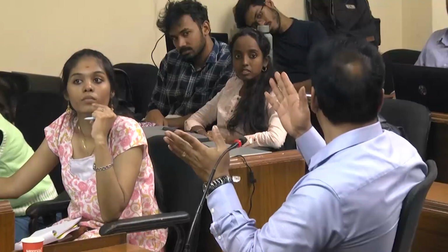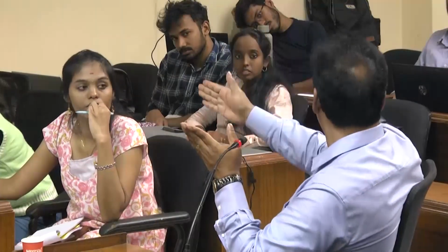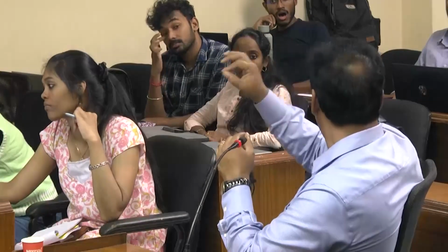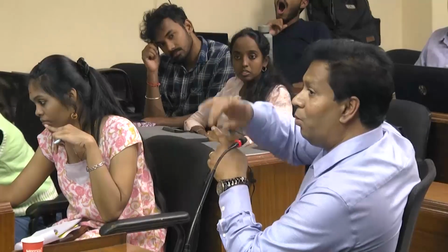So it helps in three ways. One way is if your simulation somehow stops somewhere, you can start from there. Another one is if you want to analyze some data at some specific time, because it's a transient case, you can use the data at that time. And also if you want to make some animation, you can use the whole data set and do the animation. Yes, there are three reasons.